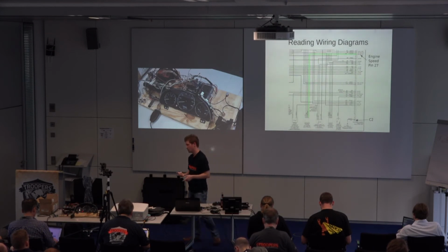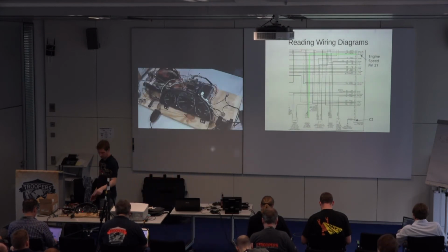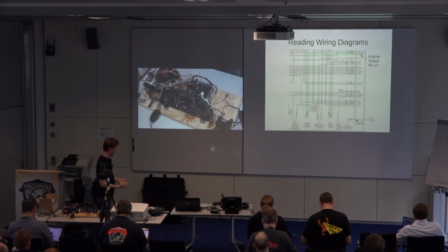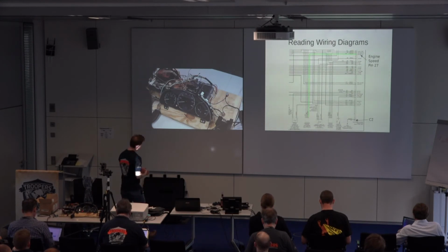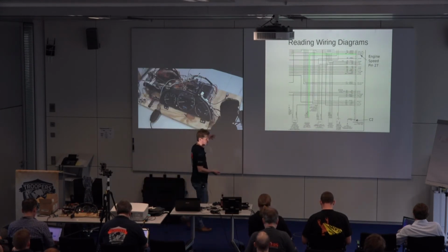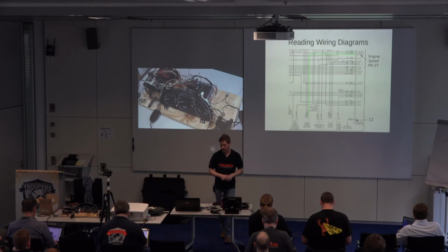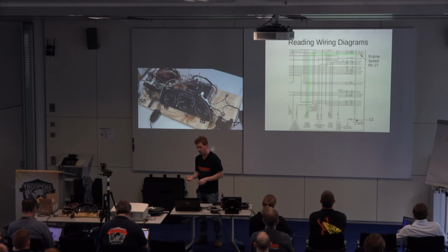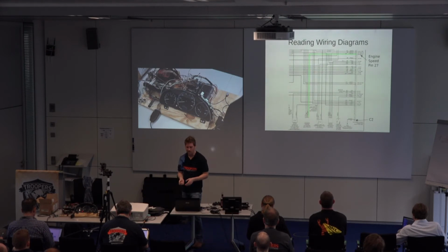Bare minimum, I mean, you can get by. My first test bench was simply just an ECU and the connector. And that's great. I mean, you'll get packets if you're making drivers. It works fine for that. The problem is you don't get a lot of feedback, a lot of control. For this particular guy, I have some extra capabilities in it for demo. And for those, you really have to look at what piece you want to sniff.